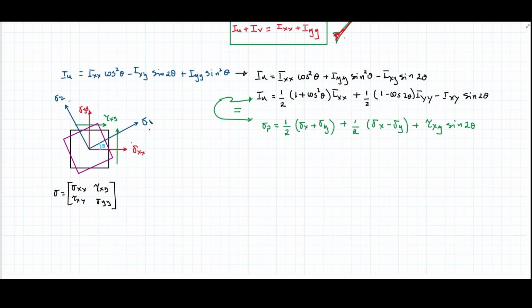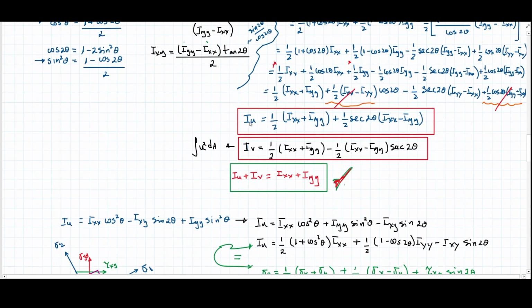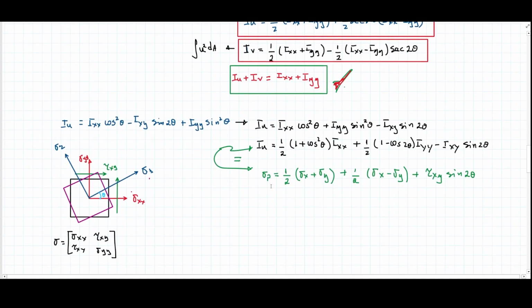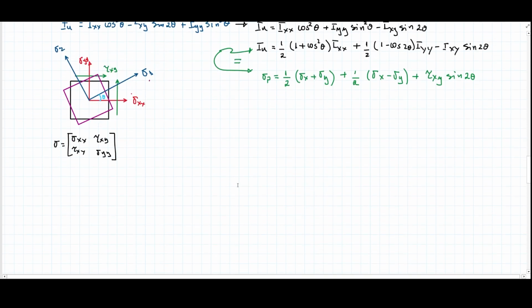Now, this is pretty similar, meaning that we are given certain second moments of area along axes that are just chosen, but that they are not the principal axis. So it means that I could use the same techniques that I used for this case, to find my principal axis if I wanted to. So of course I already have the formulas for principal axis, the moment of inertia around the principal axis. I have this beautiful balancing equation of both terms, but also means that I could use, for example, Mohr's circle to calculate from one point to another these two things, or kind of the principal axis from the axis I'm given in the obligation.